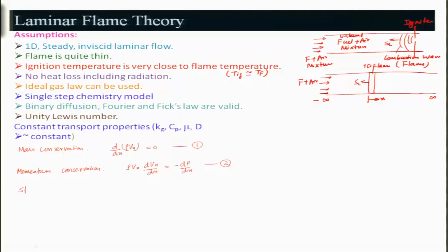And species conservation, where we will be considering the single step chemistry. In the single step chemistry model, one mole of fuel reacts with nu moles of oxidizer going to nu plus 1 moles of product. That means, having fuel, oxidizer and product, I will have to invoke 3 equations.